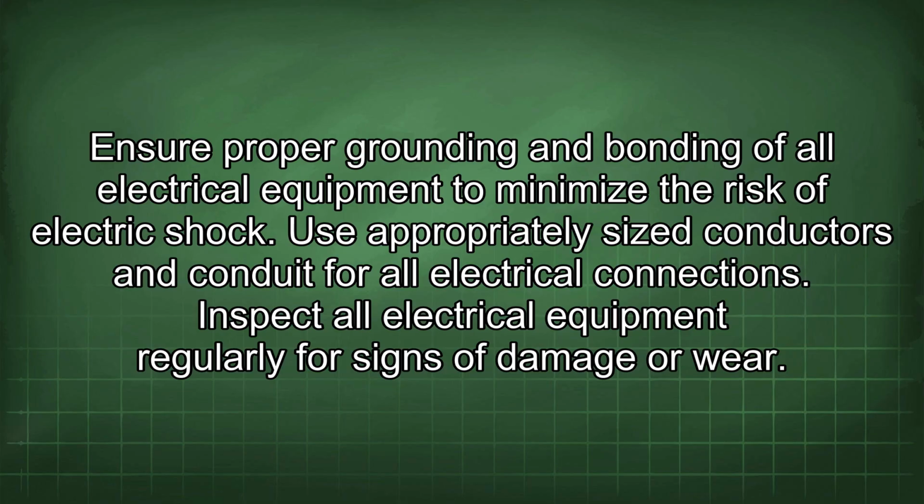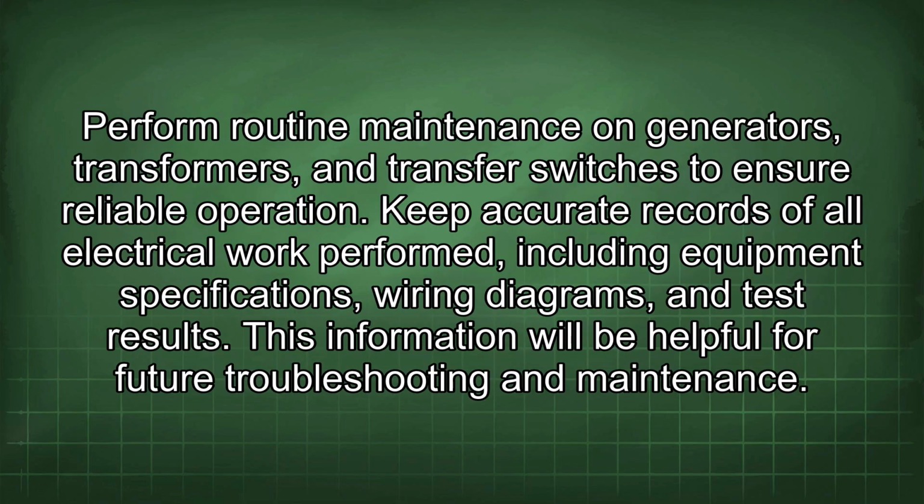Use appropriately sized conductors and conduit for all electrical connections. Inspect all electrical equipment regularly for signs of damage or wear. Perform routine maintenance on generators, transformers, and transfer switches to ensure reliable operation. Keep accurate records of all electrical work performed, including equipment specifications, wiring diagrams, and test results. This information will be helpful for future troubleshooting and maintenance.